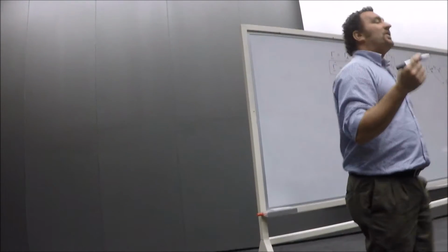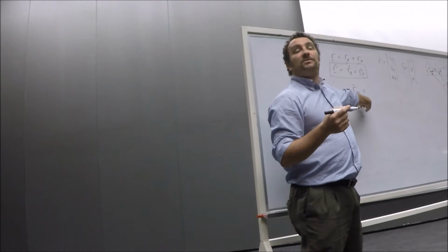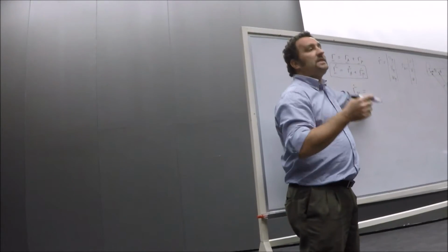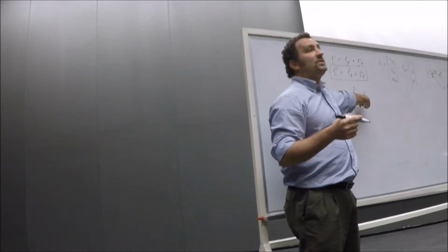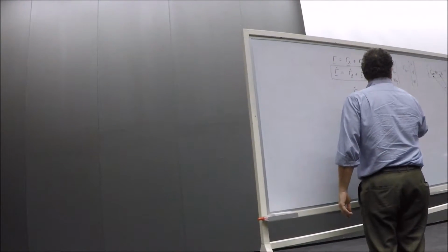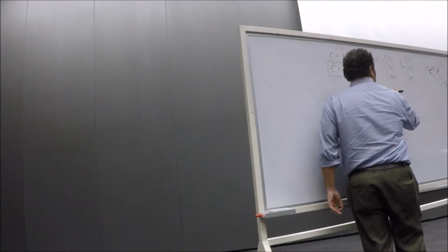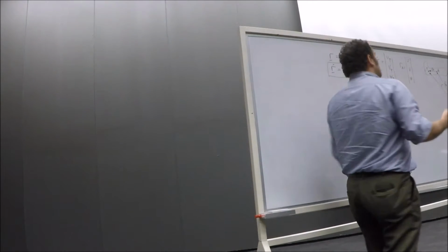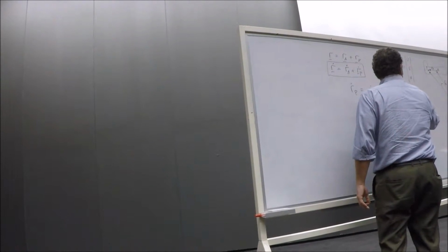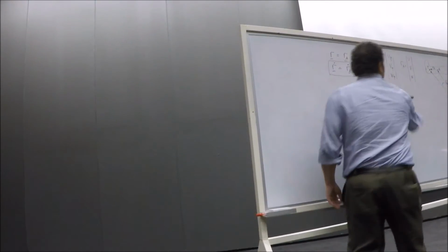So, Coriolis theorem states that the relationship that exists between the absolute velocity, the absolute quantity of a vector is equal to the derivative of that vector in the terms of the relative frame of reference plus what? The angular velocity multiplied by that vector rp. Okay?